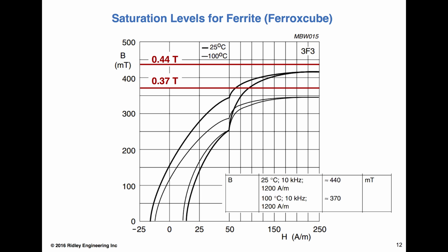Okay. Did you see the clarifying comment about pressure? Yes, I've seen that myself when you get potting in a gap or things like that. Oh yeah, absolutely. You've got to be careful with your magnetics about how you gap them. If you do the classic center leg gapping of a transformer and you make that transformer quite small, then mechanical pressure is going to fracture the legs of the core.